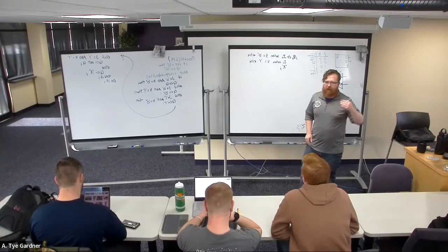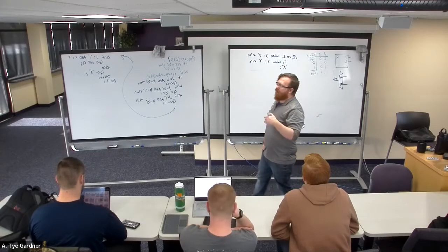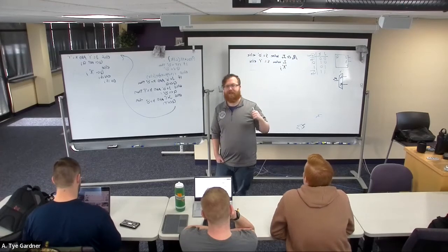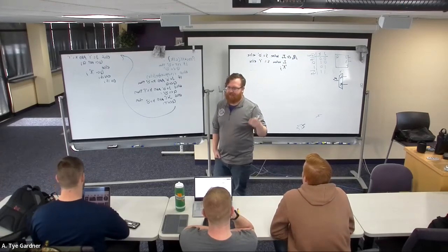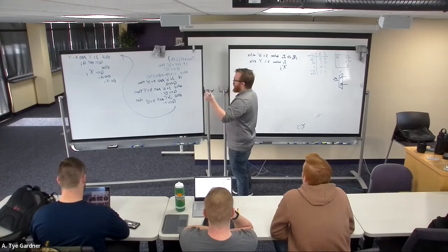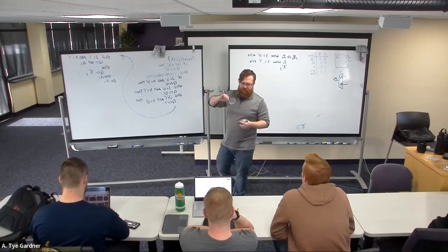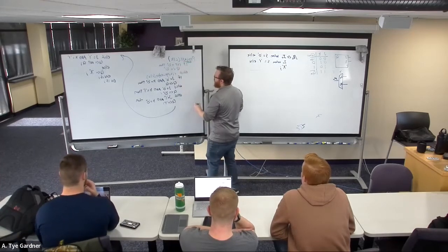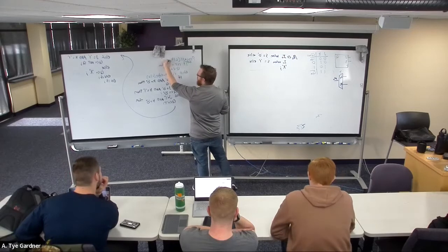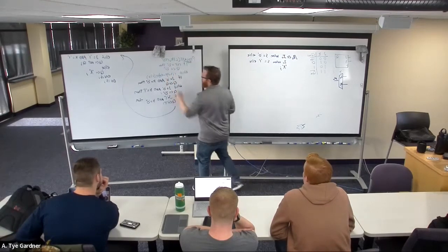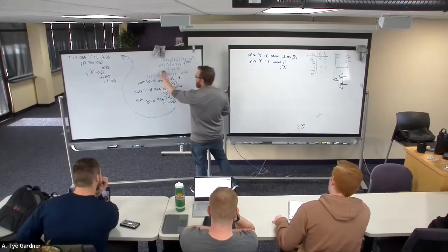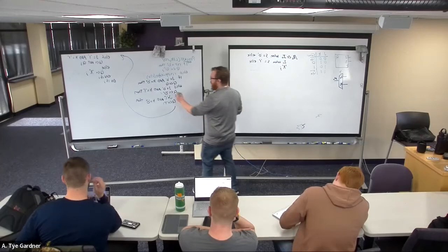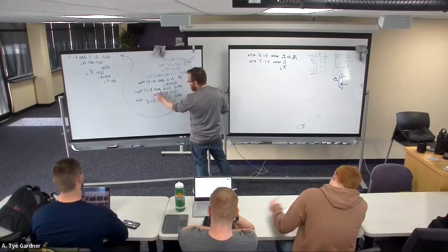The trick here is making sure that you understand the code enough that you don't start fixing errors that don't exist, right? Because then you think, oh, I got 5, I'm good to go. But if you fix something that's not there, you don't get points for it. So if this were the exam question, well, here's one. I'm missing the begin. It's supposed to be an asynchronous reset, so it needs to be in the sensitivity list. I'm missing a semicolon here. I'm missing a semicolon here and here.